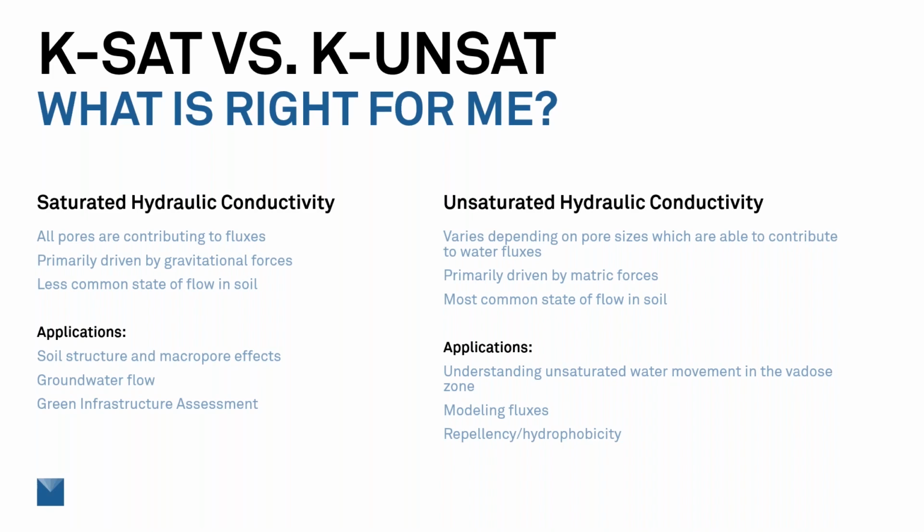So when we think about unsaturated hydraulic conductivity, you'll typically see it referenced to a given water potential or a given water content, because as that state changes, there are less pores that are able, or more pores that are able to contribute to the fluxes. So that value is going to change. And so it is a moving scale.